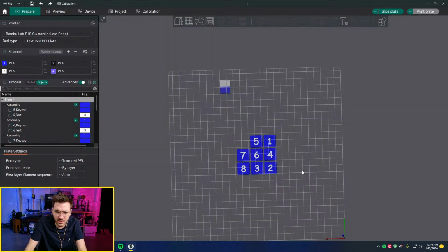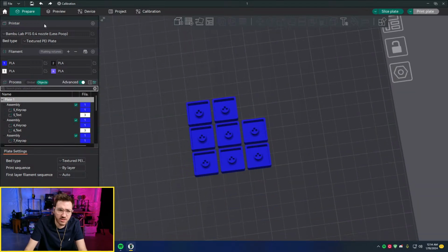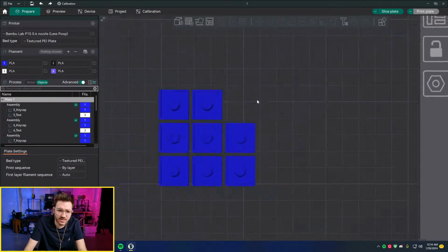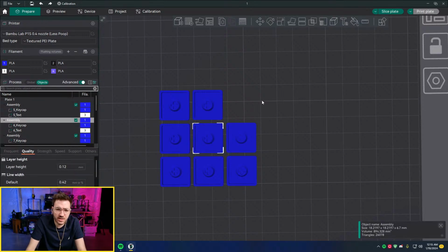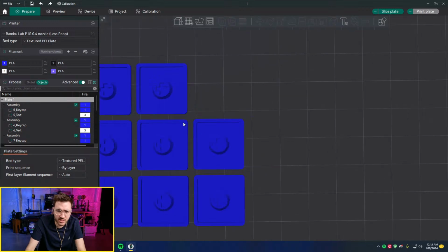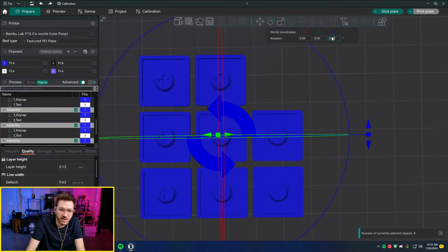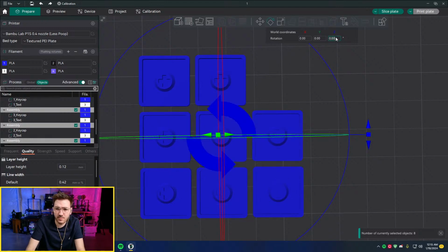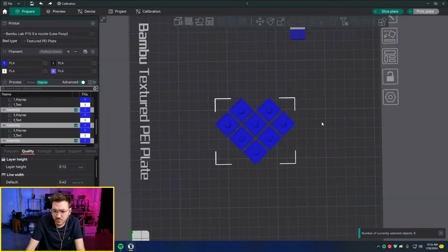Go back there. Okay. So yeah, those are the keycaps. And the thing with these flat caps, in order to get them to print right, because they have like a skew to them, you can kind of see it right here. They kind of like to rotate on the stem. So what I do is they're rotated by default. They're 0.625 rotation clockwise, so you can kind of see they're not perfectly aligned. But I also select them all, and then I print them at a 45-degree angle. So I print them like that. And I'll select these all and then center them also. And that just kind of helps.